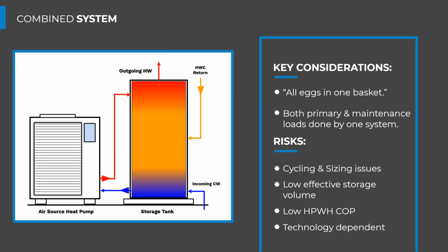A lot of energy goes out when we have a draw in the system, and we're only losing a little bit through circulation, but it's all year long, so it adds up over the course of the year. So we have a periodic, high amount of energy going out during a primary system draw, and a lower, more continuous operation with the return water.